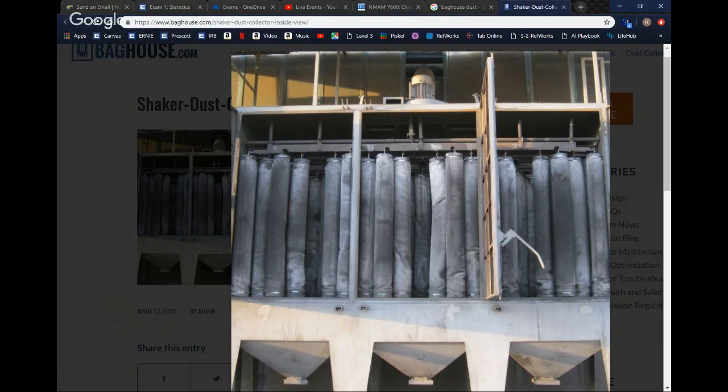So let's say you'll have ductwork down here leading to the fan, and the fan is pulling. So the air that enters here, you'll have other ducts that lead into here, and there's a bunch of dust. The air gets pulled into the sock and then down and out. And as it does, the sock filters out the dust. So the dust starts to accumulate and load onto the outside of the sock.